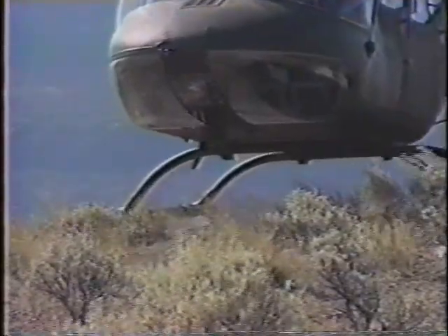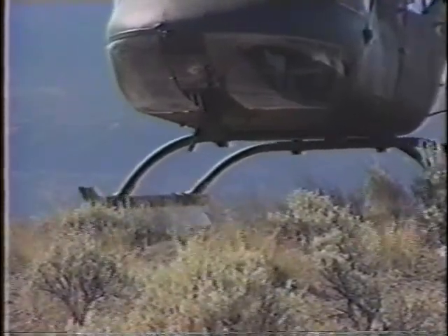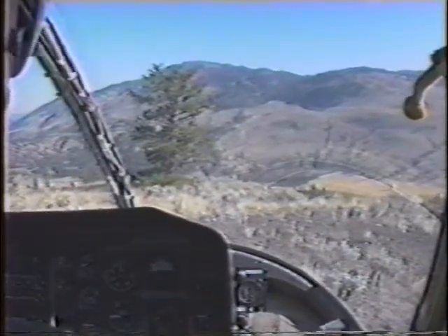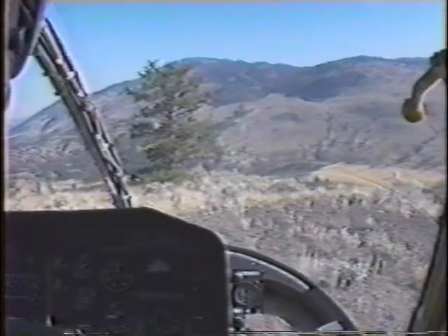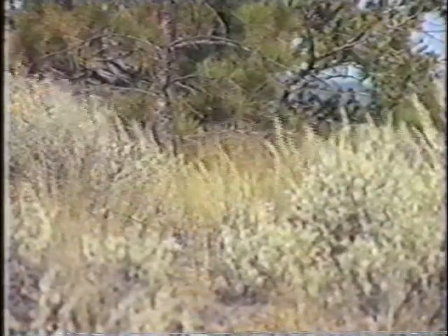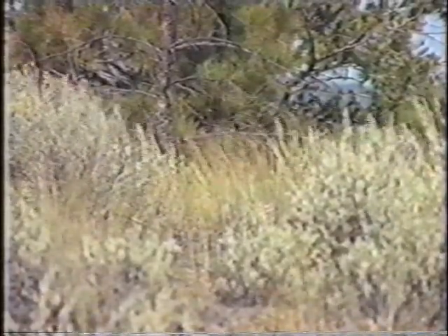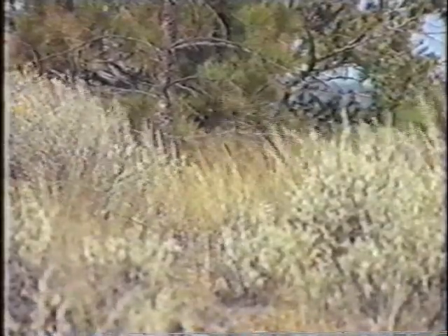Where's the sun? How is it affecting upflow now? Do some hover checks to cross-reference your available power to what you'll need. Look for the drop-off. Get to it early. And of course, check the wind. It could have changed. Even a strong, steady wind can vary up to 90 degrees. Of course, now you can set out smoke or flags if you have time to back up your other indicators.